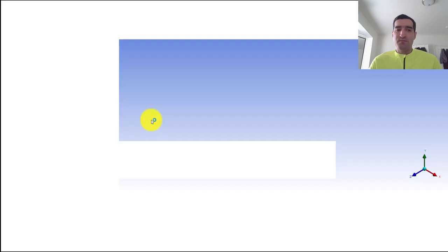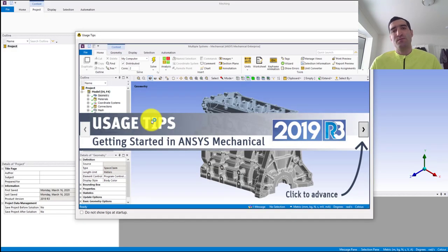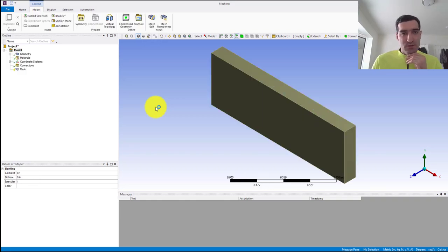If you perform a very fine mesh, it's gonna take a long time to analyze your model, and if you use coarse meshes, it might not converge. So you need to have a little knowledge about the meshing and stuff.